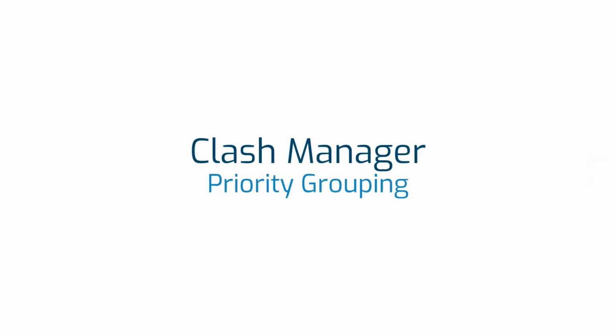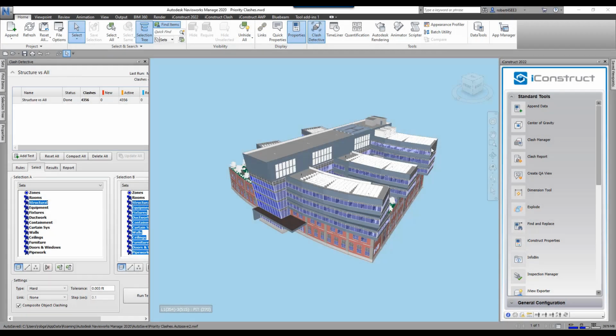Welcome to this short video on priority grouping, which is part of iConstruct's Clash Manager. Priority grouping allows you to automatically assign clashes or issues to the appropriate contractor depending on what should move first. So to demonstrate this, I have a test already called structural versus all.